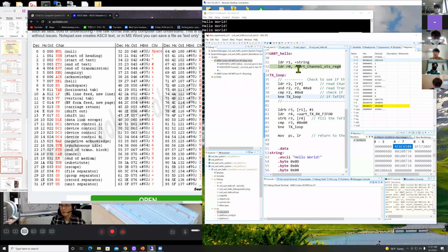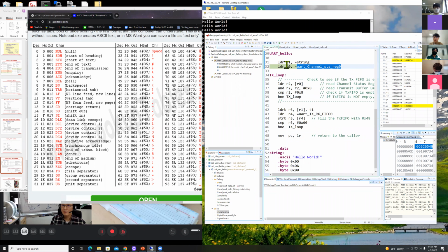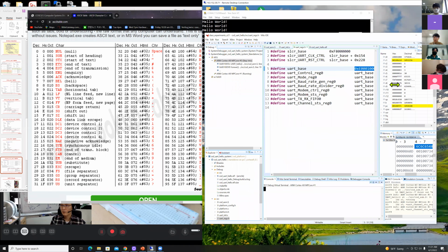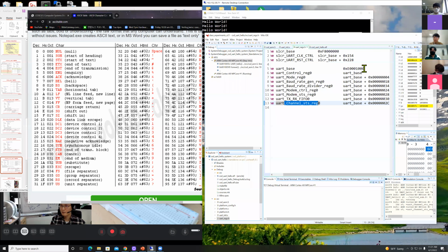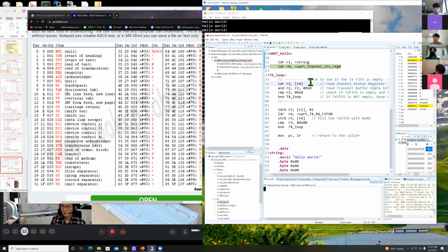Okay, so now the status register, right? The status register is defined here in the code. The status register is located at this base plus 2C. E 3 zeros 1 0 2C. Let's execute this. R1, right? R0, sorry, R0, 102C.